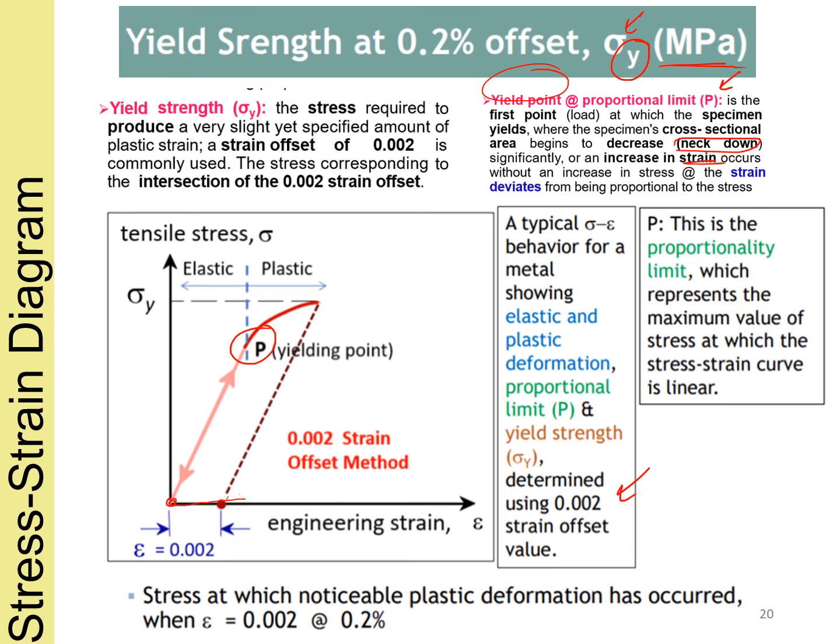You will make a straight line parallel to the elastic region until it intersects the curve over here. That is what we call your yield strength.